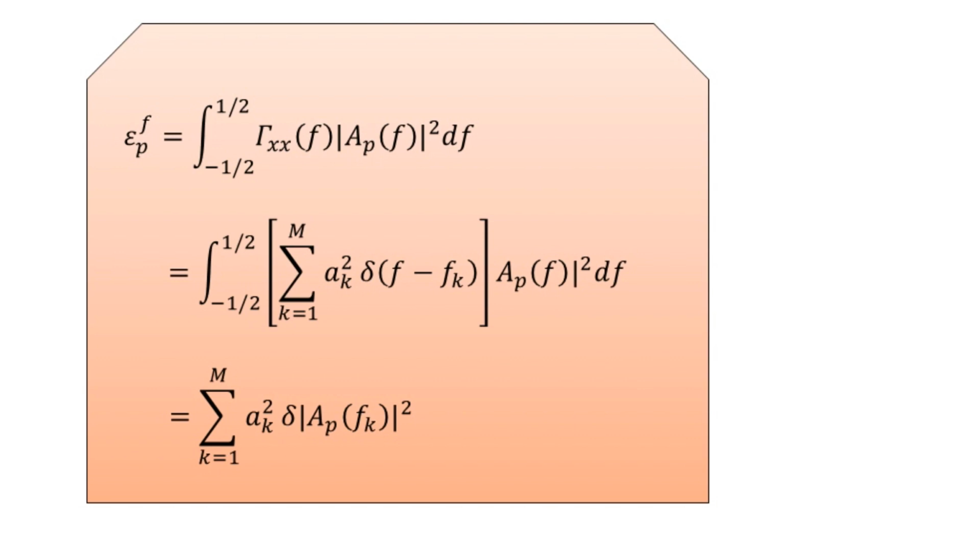So here the thing is very clear that if a random process consists of a mixture of a continuous power spectral density and a discrete spectrum, at that time the prediction error filter must have all its roots inside the unit circle. After completion of this first property, let us have the second property, with the title maximum phase property of the backward prediction error filter.